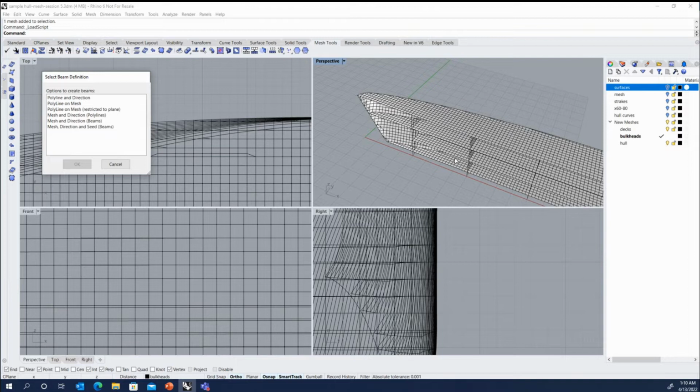You could probably pick about a 45-degree angle so that they're all pointed towards the inside of the hull, but some are a little bit skewed. They're not perpendicular to the plate. So what you can do is tell it, I want it to be normal to the plate, but restrict it to either the constant X, constant Y, or constant Z. So that's handy for writing out frames.